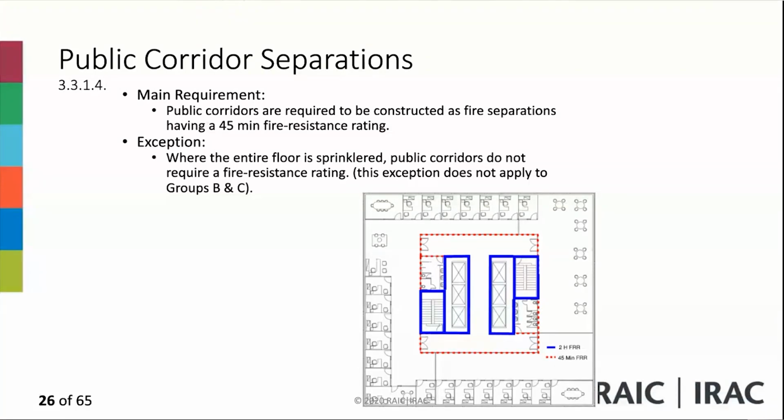The story is sprinklered throughout, and no fire resistance rating is required for a fire separation between a public corridor and the remainder of the story, provided the corridor does not serve a care, treatment, or detention occupancy or a residential occupancy.